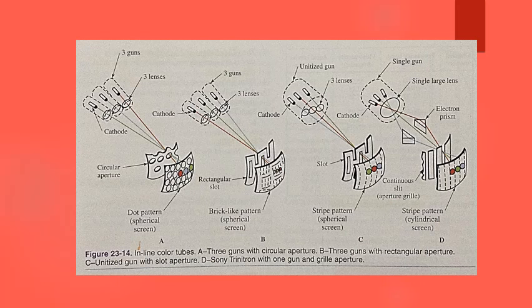A line is made by one complete scan from left to right, with all 3 electron beams hitting the dots across the screen. If all the electron beams are adjusted properly, the result will be a white line. A color line is made by mixing the electron beams.